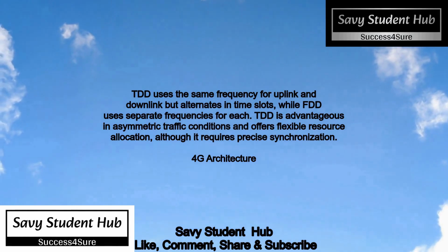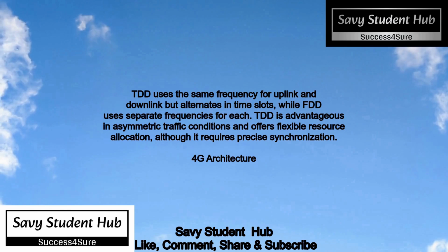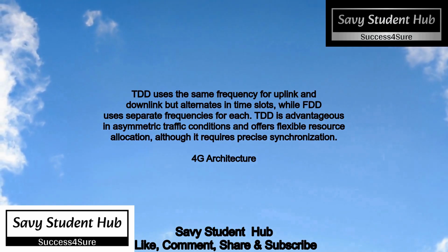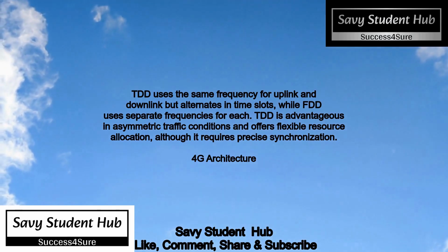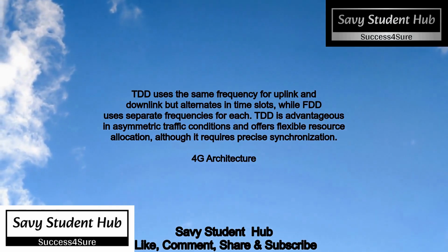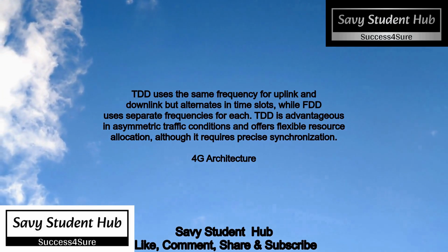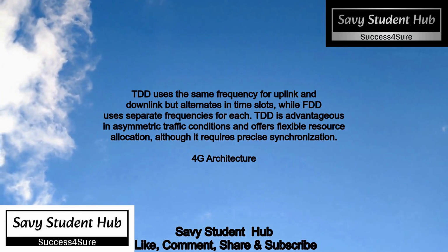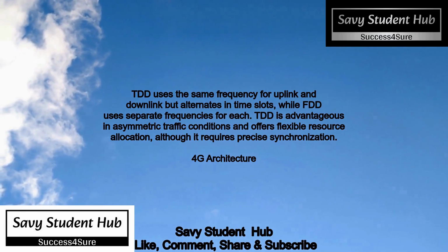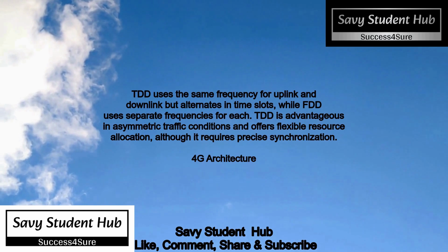TDD uses the same frequency for uplink and downlink but alternates in time slots, while FDD uses separate frequencies for each. TDD is advantageous in asymmetric traffic conditions and offers flexible resource allocation, although it requires precise synchronization.